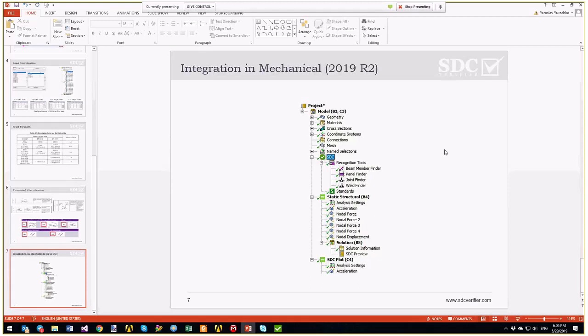And the other question is, are there any checks for solid elements? Yes, you have. For solids, any result, basically the checks are based on results you get from Ansys. So solid results, stress results can be used as well. Plate buckling and these kinds of things is hard because plates we cannot recognize, but we can do, for example, fatigue analysis.